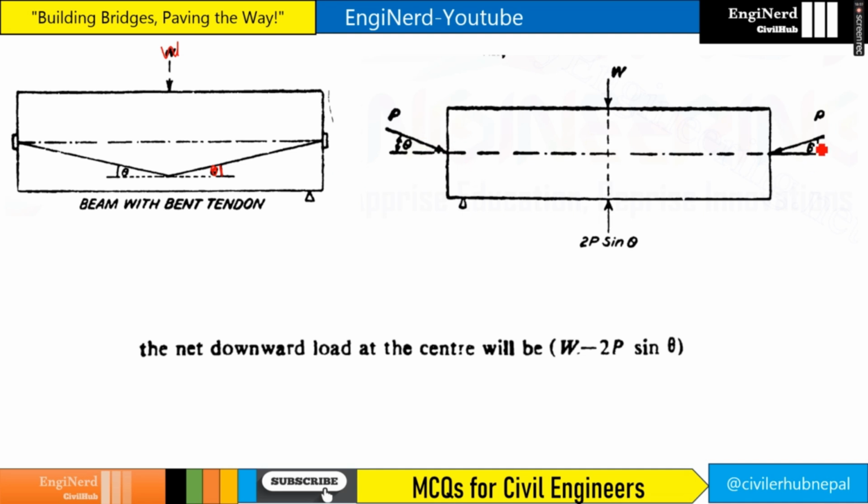So this has to be theta degree also, right? This has to be theta degree, and this P will produce a uniform upward force, right? So if it provides uniform upward force, it will be P sine theta from here and P sine theta from here, right? So it will be 2P sine theta, and this is in the downward direction and this is in the upward direction.